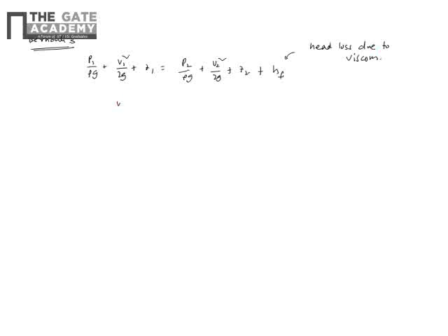Now this is what we got, an equation between shear stress and the pressure variation. Let's now derive an equation for the velocity distribution, and from there how the flow rate will be affected by the pressure loss. So let's apply the Bernoulli equation. Remember this is a real fluid, so we need to consider the head loss due to viscosity. Now v1 equals v2 from continuity, and z1 equals z2 because it's at the same level. So what we get is (p1 minus p2)/ρg is the head loss.